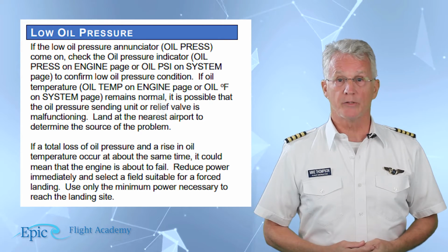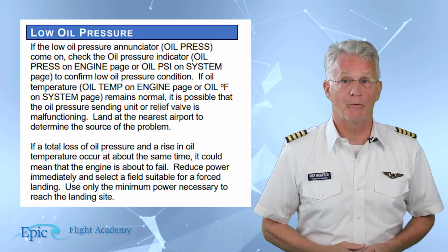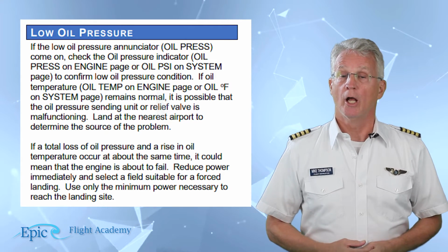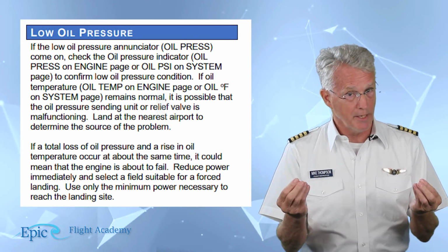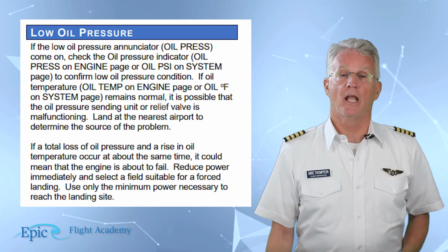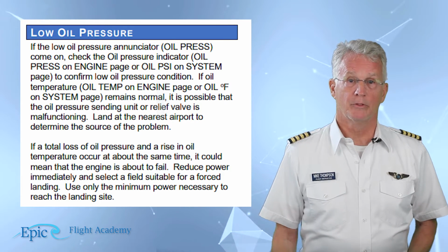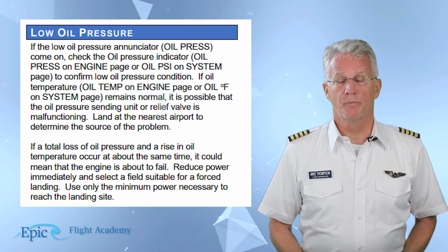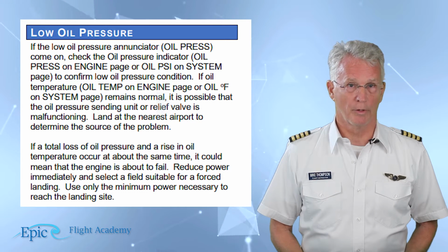If a total loss of oil pressure and a rise in oil temperature occur at the same time, it is very likely that the engine is about to fail. So reduce power and plan accordingly.